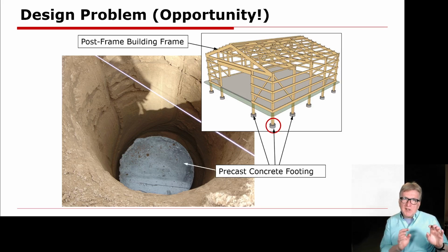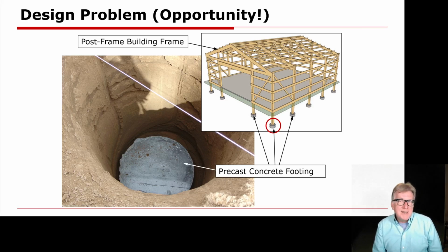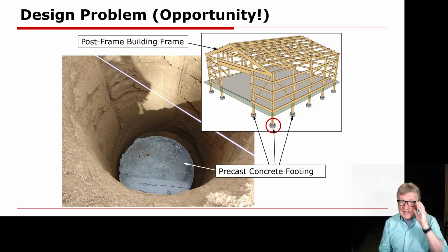I'm going to refer to these as either concrete footings, or some people sometimes refer to these as cookies. They're not really a cookie. I mean, they're a round shape like a disc. But these things are heavy. They weigh typically anywhere between 180 and maybe as much as 300 pounds. The benefit of the footing is obviously they form a foundation for those posts. Especially on loose soil, they spread the force out over a larger surface area. So there's lots of benefits.